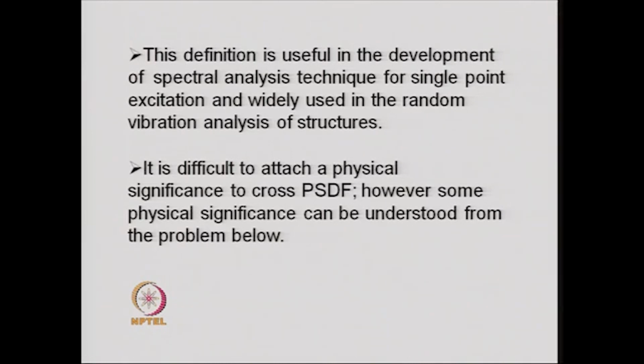That is, the area under the power spectral density function curve is equal to the mean square value, or alternatively, the distribution of the mean square value with frequency is the power spectral density function. So, that gives a physical sense to the spectral analysis.